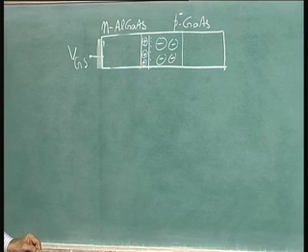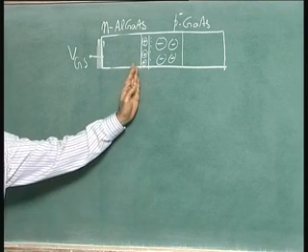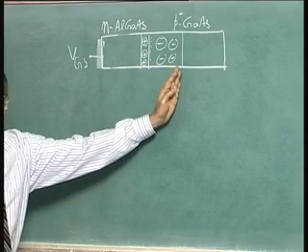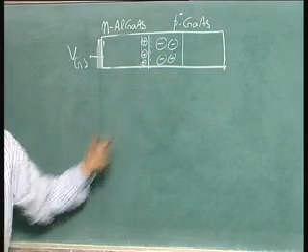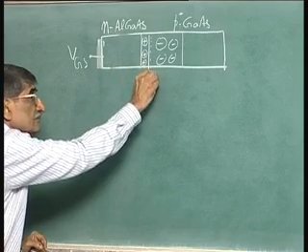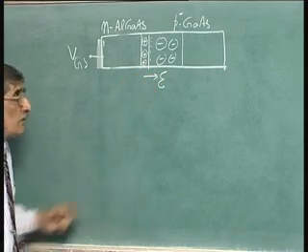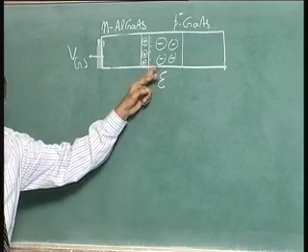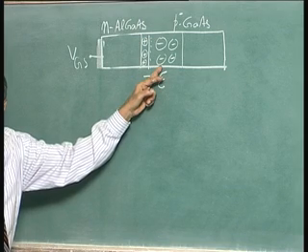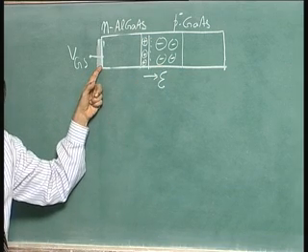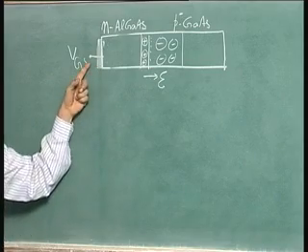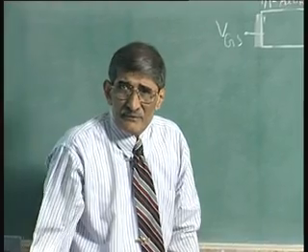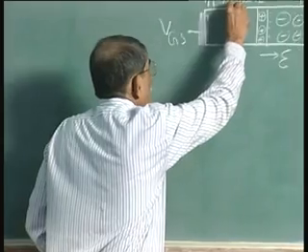Okay. Now, this part of the depletion layer is part of the p-n junction. So, electric field is in this direction here, all the field lines originating here terminate on that side. Now, the Schottky barrier, okay, if I apply negative voltage to the gate, to the built in potential itself, there will be a depletion layer.